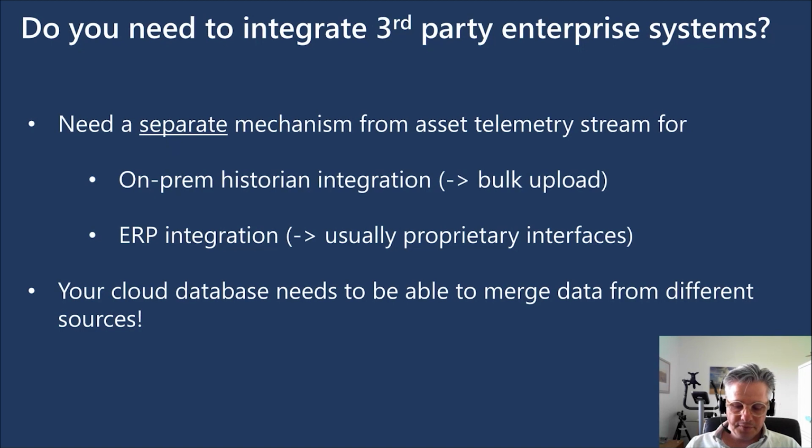They also, obviously offer an OPCUA interface on the back end, so you can connect through OPCUA to those software assets, and it makes it much simpler than to again do that data standardization. Similar with ERP systems, they usually have proprietary interfaces, and you just need to bite the bullet and create a converter, right? Extra points for converting into a standard format.